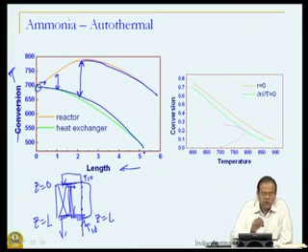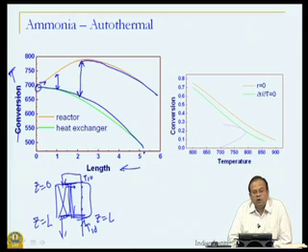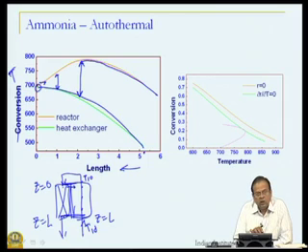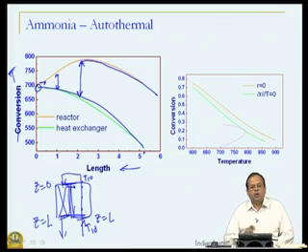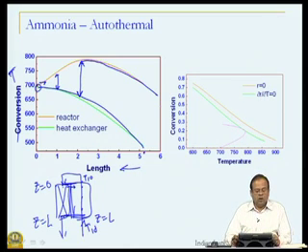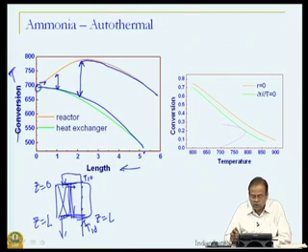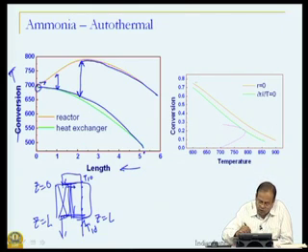Now, this is what we wanted for our reversible exothermic reaction anyway, that is high temperature in the beginning and progressively decreasing temperature. So, this is how it is achieved by a single operation in which you preheat your reactant using the energy that is generated in the reaction. If you recall our discussion on extent of reaction and temperature, this is how things work here.